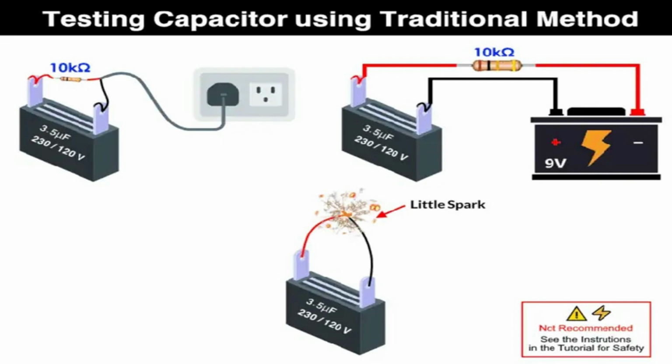Please be careful to do that and make sure that you have worn safety goggles. If it makes a strong spark, then the capacitor is good. If it makes a weak or no spark at all, then it is a defective capacitor. You would have to change it immediately with a new one.